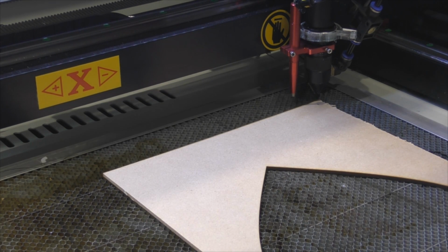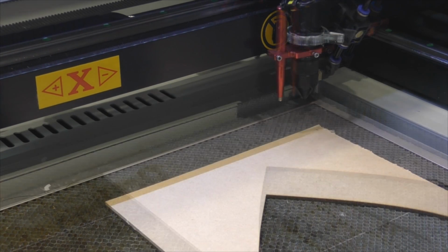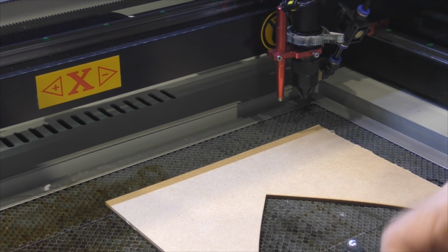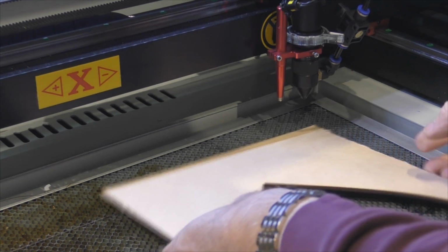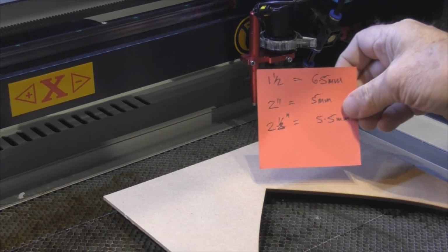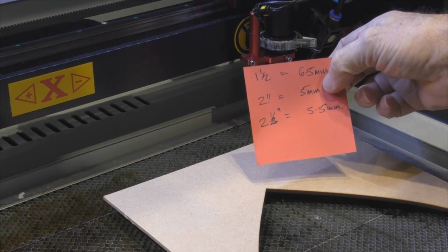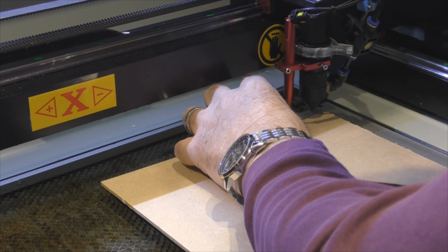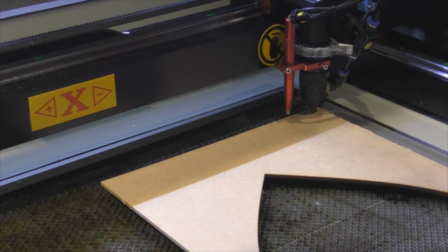So what I'm going to do is to pack that job up onto little packers. Now, I've mentioned to you before things like these. These are dome nuts. Anything will do for packing up. And then on this 2-inch lens, I need to set the focus to 5mm above the surface. There we go. So we're basically set up now, but what we haven't done is set any parameters.